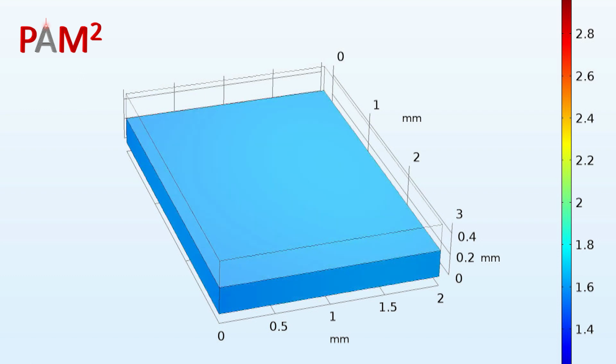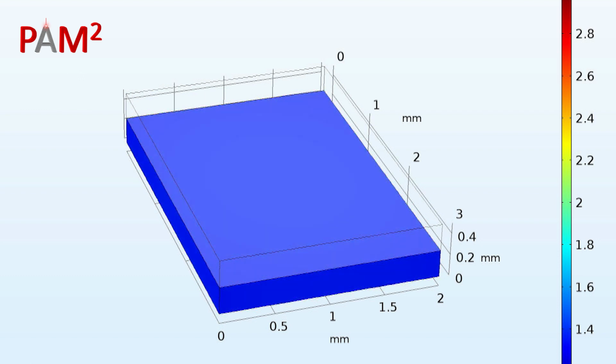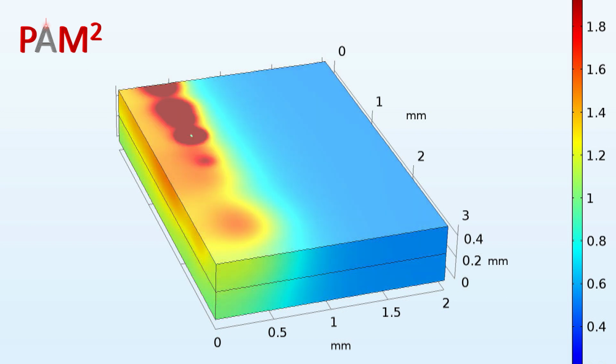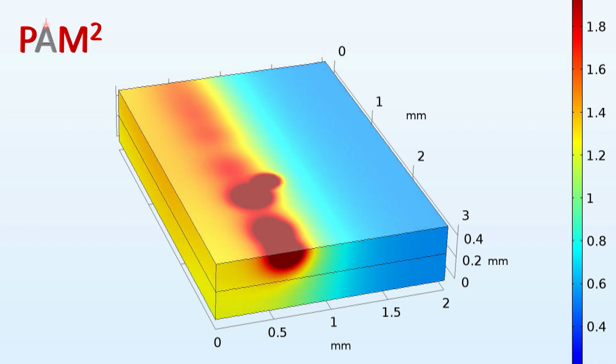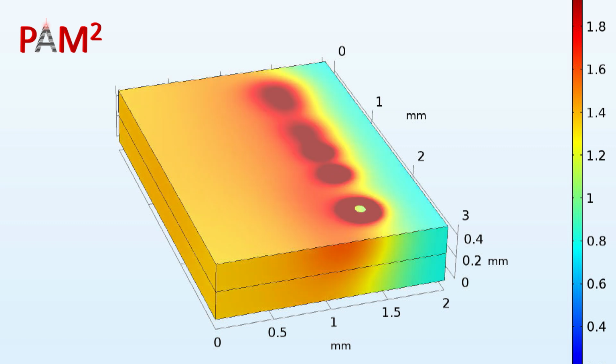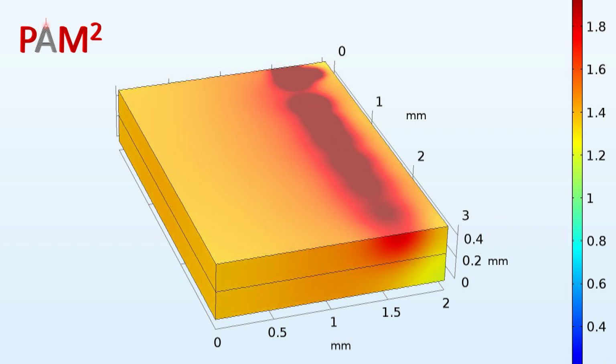After the scanning of the first layer, it cools down for 2 seconds, where the average temperature goes down to around 1000 degrees Celsius. Then the next layer is established, and again the laser starts to scan it. But this time the temperature is higher than the first layer, due to heat transfer from the previous layer which had already been established.